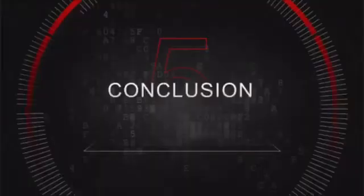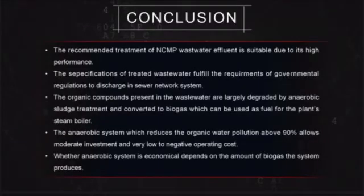So for the conclusion, the recommended treatment of NCMP wastewater effluent is suitable due to its high performance. The specification of treated wastewater fulfills the requirement of government regulation to discharge in the sewer network system. The organic compounds present in the wastewater are largely degraded by anaerobic sludge treatment and converted to biogas, which can be used as fuel for the plant's steam boiler.